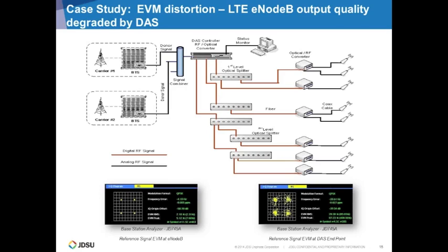And this is something that is prevalent and can happen within a DAS system. Not only can it happen to the signal quality, but we've also seen where cables have been swapped, meaning that you don't have the MIMO that you expected, and there's different levels of what kind of impact that can have to the end user, or simply just a diversity alarm where you may be replacing the wrong antenna. We've also found on these case studies where we've seen timing of the two transmits for MIMO are in fact not within the specifications of what 3GPP requires.